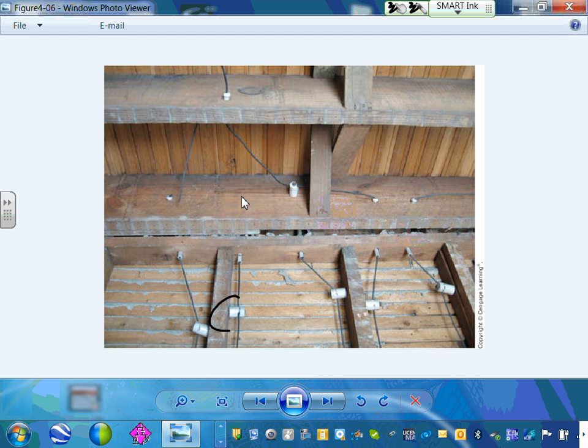So here's my number 2. Can you guys see? This is a hot and this is a neutral. There are 2 different wires. That's a violation of the code. They're not bare. No, they're covered with an insulation that deteriorates a lot. So it's really dangerous. They're still working though. You'll be surprised how many homes in the U.S. are still running with these wires.